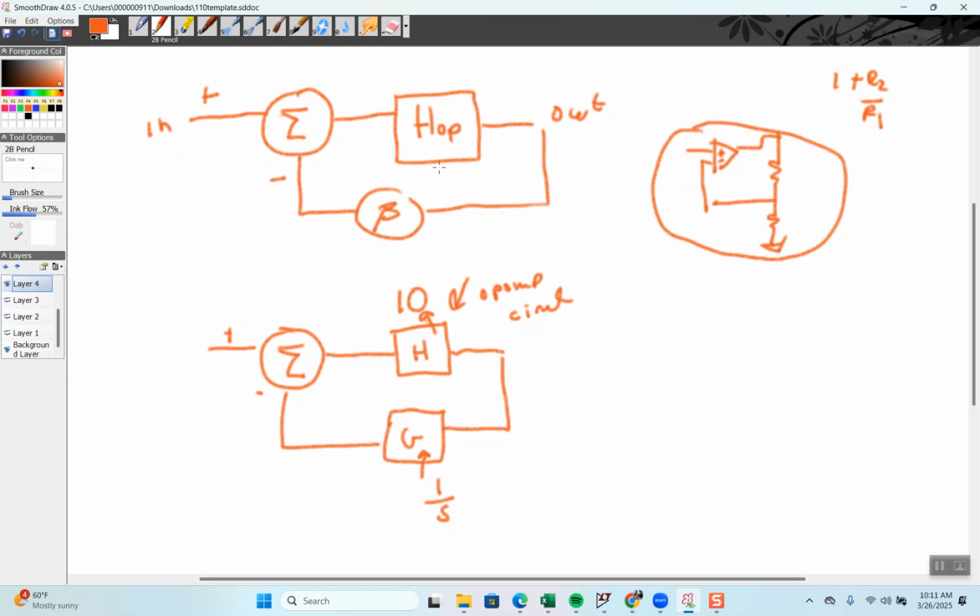But am I going to substitute this whole transfer thing into here? No, that'd be too complicated. I'm just going to say 10 because I assume everything is ideal. Then when I build it and simulate it and it's not, well, I know it's gain bandwidth. And then here, right, it's 1 over S. But the only thing that does that easily is this, minus 1 over S. Capacitances and resistances all selected to make 10 and 1 over S.